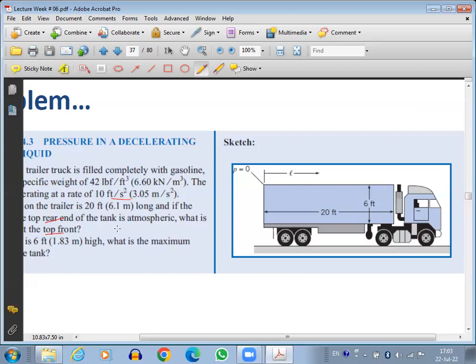So if you quickly move it, the water level would vary. These water levels, which were initially horizontal, if you are moving like this, it will become like this. If you are moving the other way, then the water level will become like this. Now in this case, these water lines are the constant pressure lines. So the constant pressure lines were horizontal when it is stationary, but if it is in motion, the constant pressure lines vary. The constant pressure lines tilt according to the motion. Now, just imagine it.